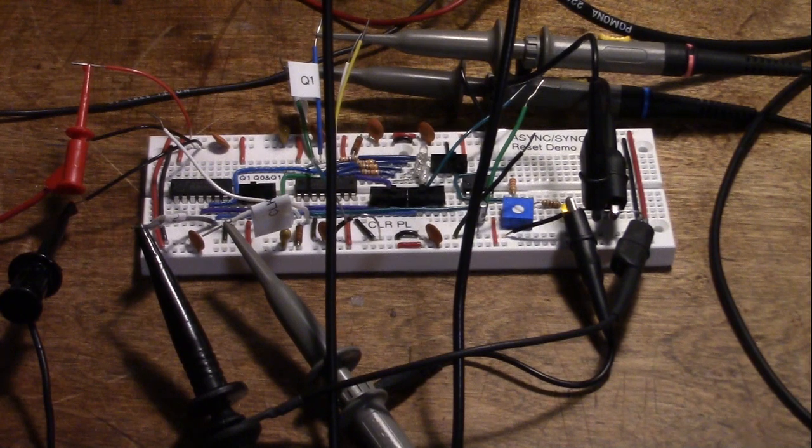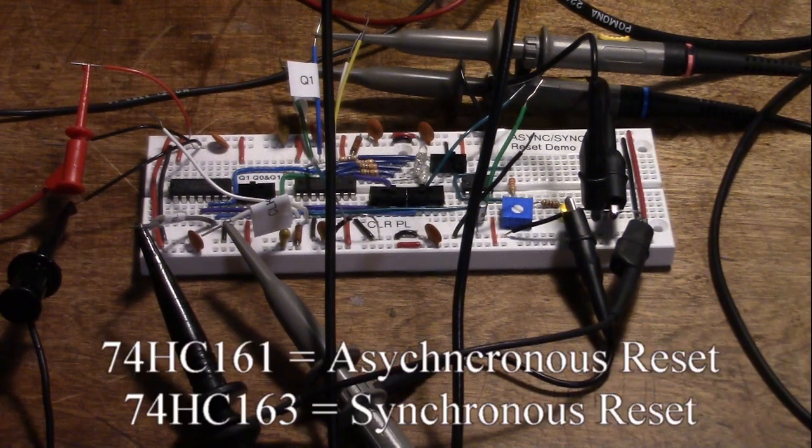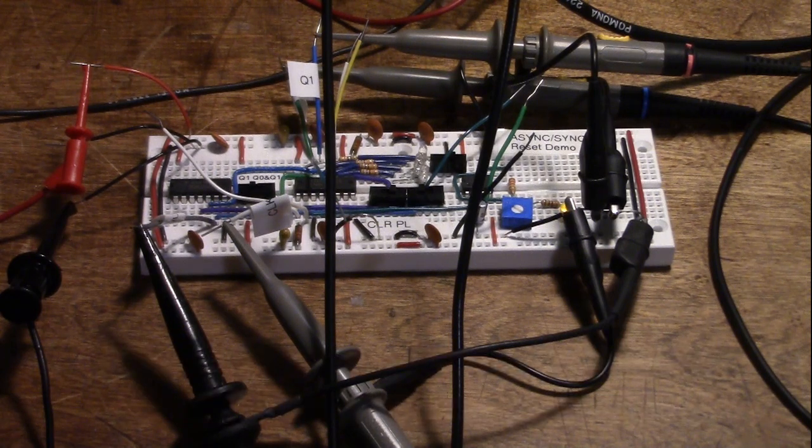We're going to take a look at the difference between the asynchronous reset on the 74HC161 and the synchronous reset on the 74HC163. As you'll remember, that's the only difference between these two counters. They're both binary synchronous counters. The counters themselves are synchronous. They use the same clock on all the flip-flops. The difference is how they reset.